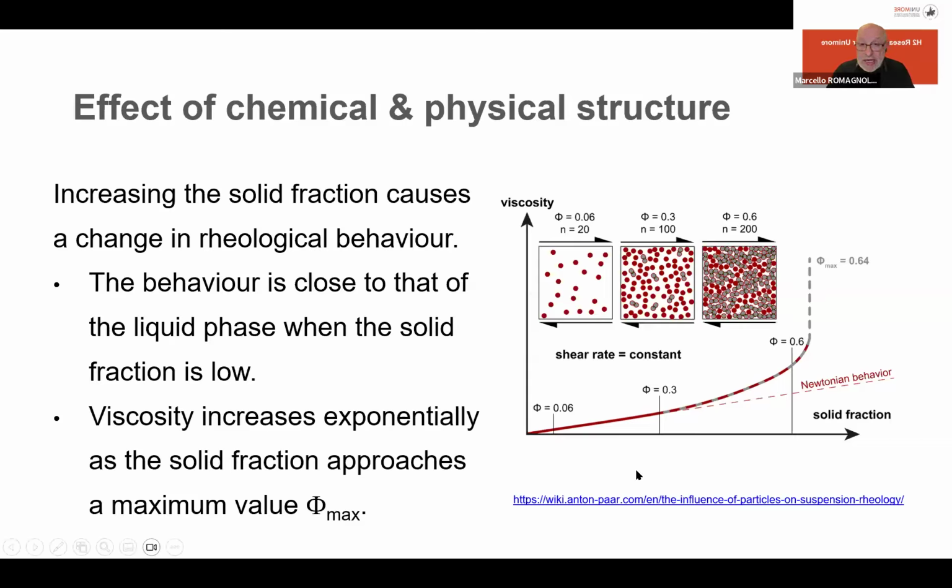At low concentration, for example here, we have an almost linear behavior. But as we approach the maximum packing limit, which depends on several factors, it's not a constant value, and it's not constant for all ceramic systems, the particles start colliding with each other, the friction and mechanical constraints take over, and the viscosity diverges sharply and increases a lot.